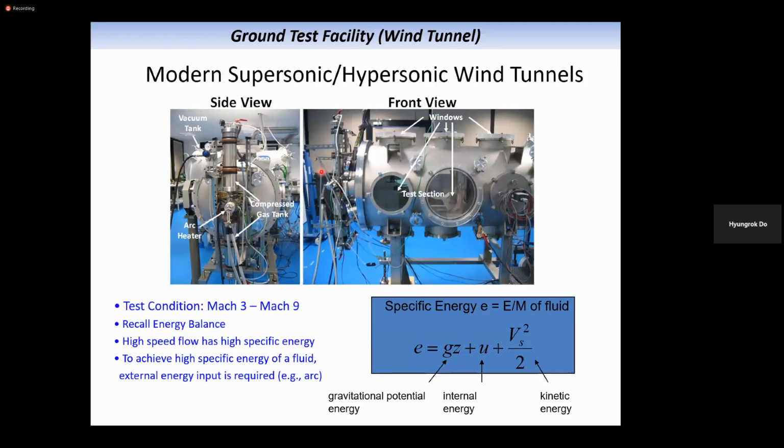All right. Here is another possible heater you can use for generating high temperature and high pressure gas. That is arc plasma. Arc plasmas can generate temperatures above tens of thousands of kelvins. So it is an extremely high temperature, and most devices will melt down. Accommodating an arc discharge or plasma discharge in a vessel is quite challenging. So the other option is generating the arc plasma for a very short time period, or you can isolate it with a magnetic field. You can choose that, but it's not the main interest of this topic.